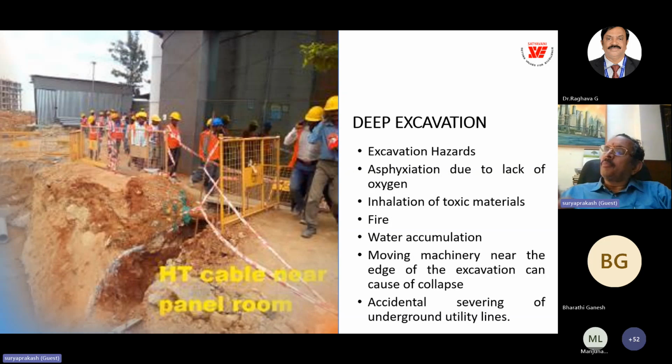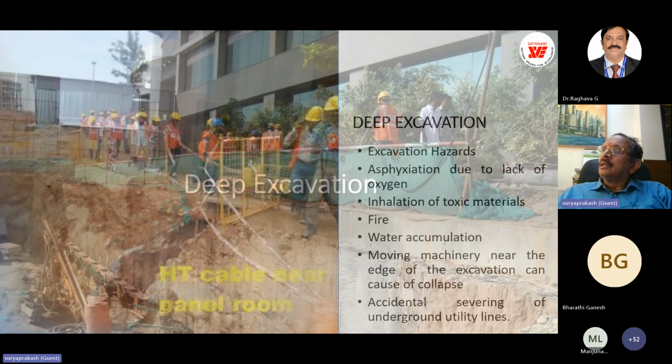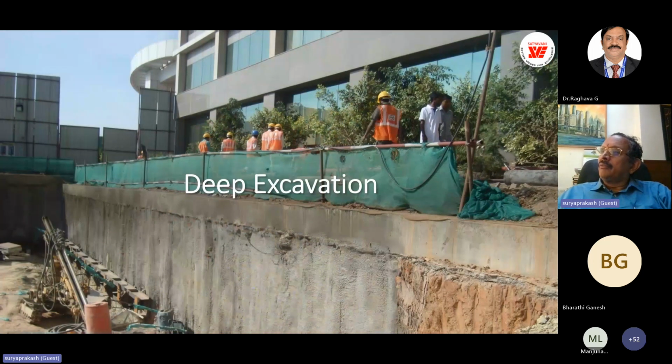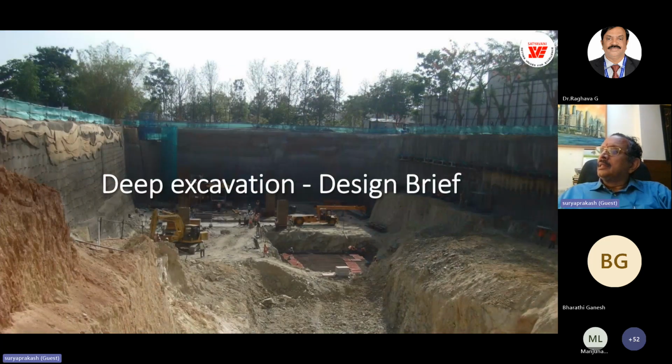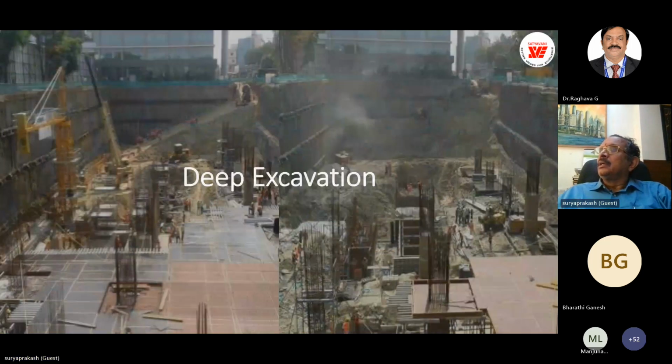But in the same project where we had the uniform soil strata, the shoring piles worked, but where we had this soft disintegrated rock, we had the problem of misinterpretation of the soft disintegrated rock as hard rock. And then this is the deep excavation before failure. These are all the piles, shoring piles with the cap. And this is the deep excavation where we had the uniform strata of the soil, where all the 20 meters deep excavation worked perfectly.